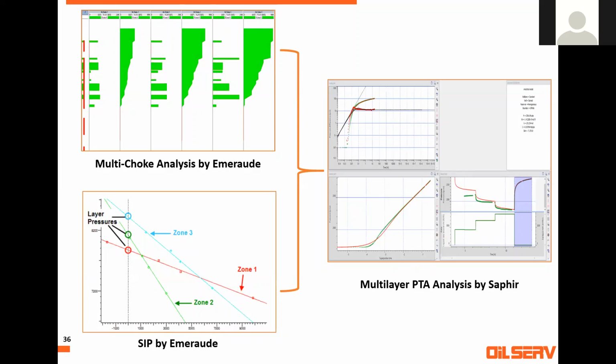Because what's happened? Let's assume you are producing at a single flow rate for a long time. You didn't agitate your formation really. But when you make a different flow rate, maybe increase it, you agitate some different pores in it. So the pressure wave will be changed, will agitate the formation. You'll get more information from the data.